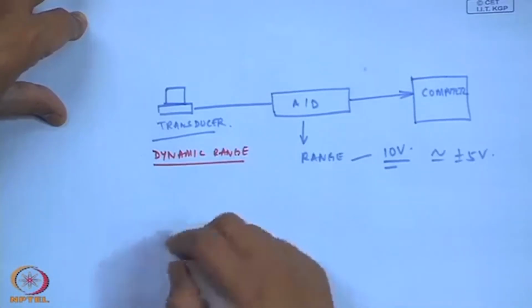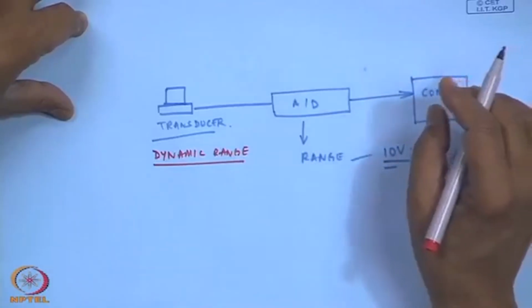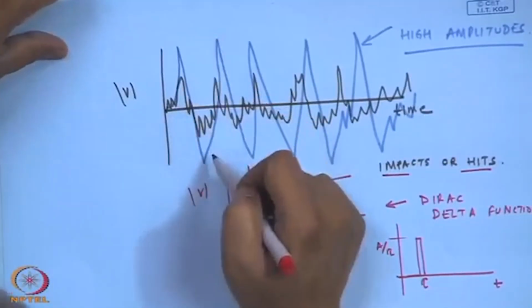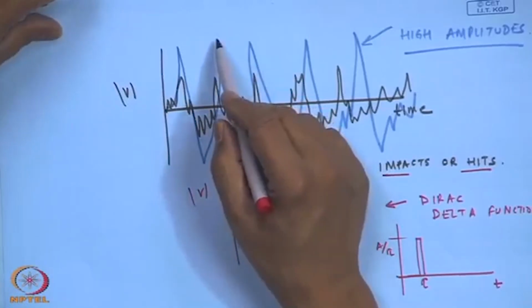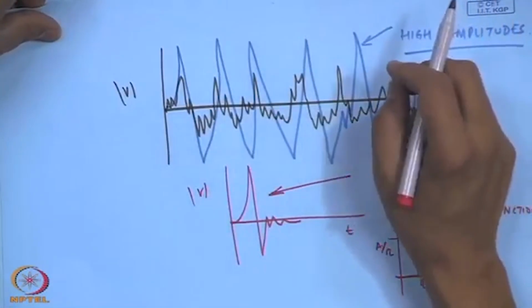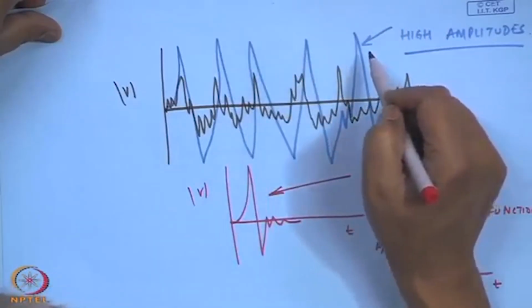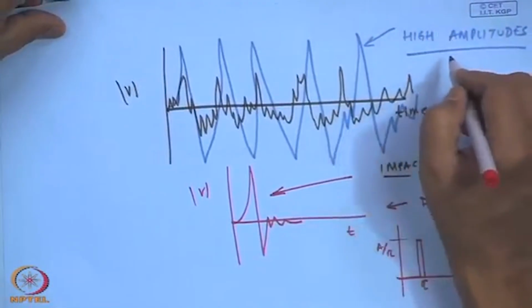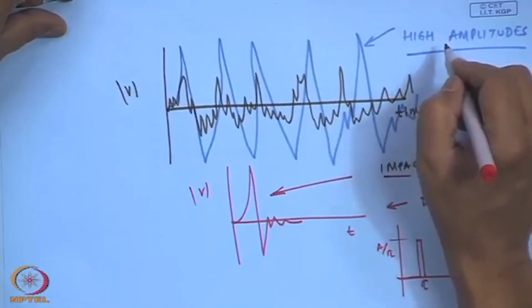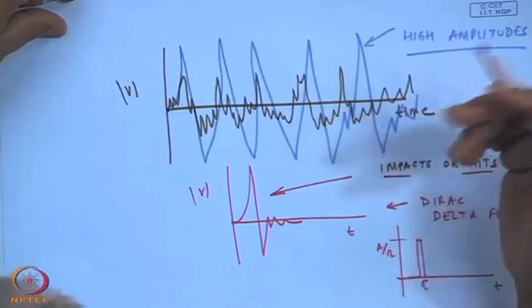It must have happened because of this impact, because there is no physical device which is controlling this amplitude. There is no limit to controlling, because if I have an impact because of a looseness, it is going to produce a high vibration signal, and this is limited by the dynamic range of the transducer. Sometimes it may go beyond the dynamic range, it may overrange.